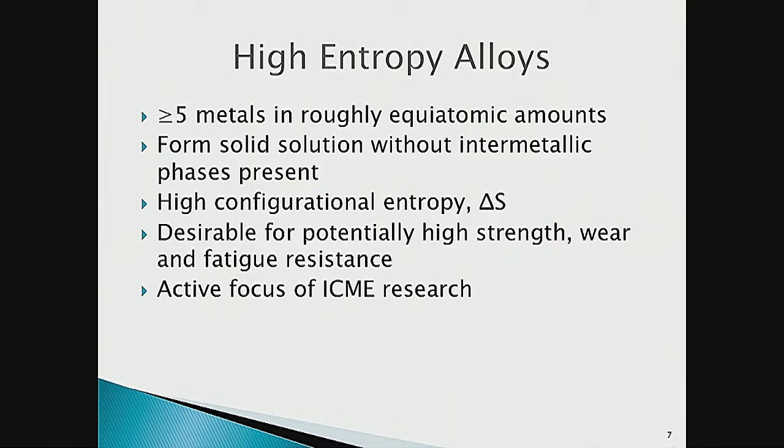Now the nice part about these alloys, of having this very high entropy and this solid solution type structure, is they have a number of desirable properties. They can get good wear resistance, good fatigue resistance, and pretty high strength compared to if you just take one element, stick it in another element to form an alloy, and just get that combination.